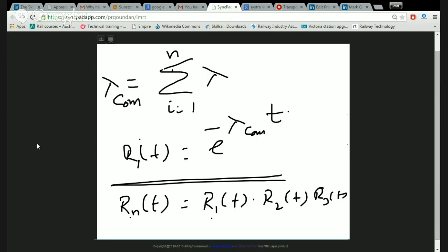How do you verify your design is right? You manufacture a prototype, subject it to test. Testing methods we saw. You test up to time t, note down the failures, or test until r number of failures occur. Total time you know, failures you know, failure rate you know. So that failure rate and what you have predicted, if they are the same, fine.